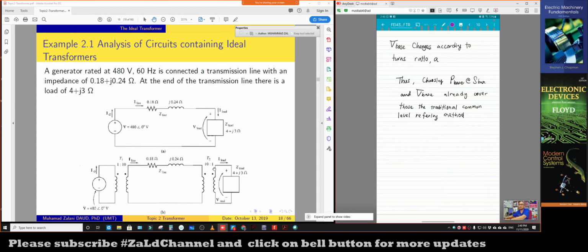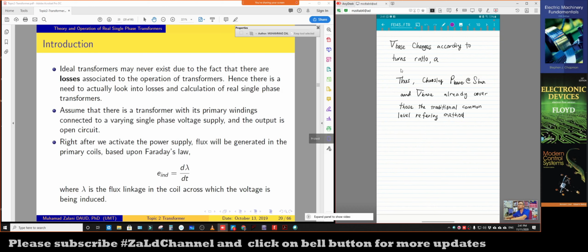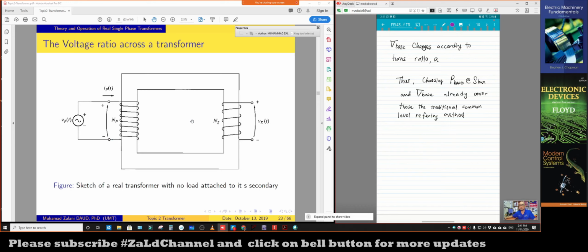In the previous method, we eliminated the receiving end transformer, and then we eliminated the sending end transformer, right? So in that case, we eliminated the transformer to represent it in terms of another equivalent circuit. But in this case, once we choose the V base and also P base, we have actually already covered all those things. So there will be no need to do the elimination of the transformer. That stage will not be needed.